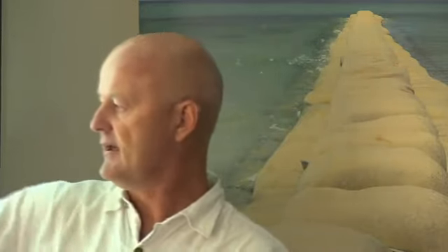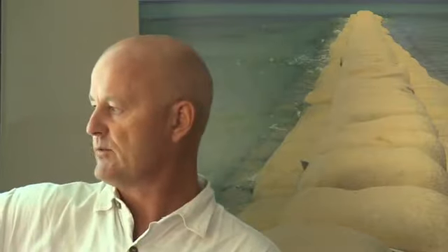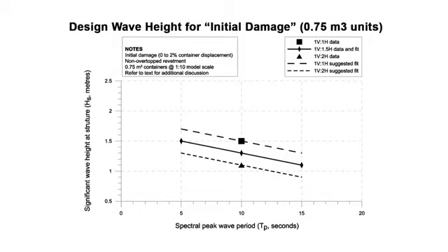Physical modelling is not an exact science, it's still not 100% repeatable. We can find a case here that withstood 1.7 metre waves, but generally once we go above 1.5 metre waves, we start getting damage, 4 or 5% in these cases. So for the design curves, we set that as our initial damage threshold. You can see there's definitely no damage below it, and generally there's damage above that threshold. So that's a 5-second wave. Just bear in mind that damage occurs at about 1.5 metre wave height.